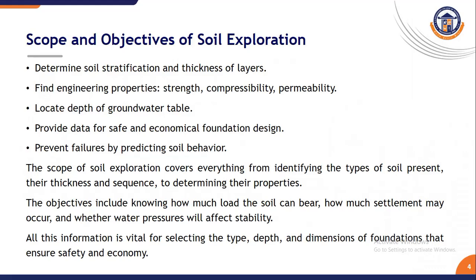The next topic is the scope and objectives of soil exploration. These include determining the soil stratification and thickness of the layers, finding engineering properties, that is, strength, compressibility and permeability of the soil, and locating the depth of the groundwater table.